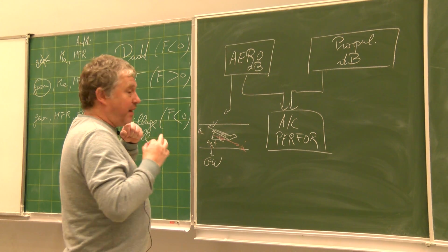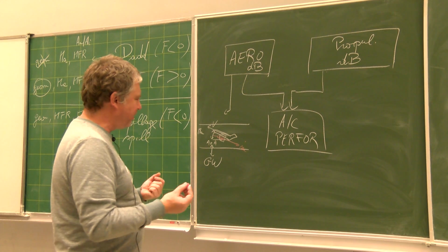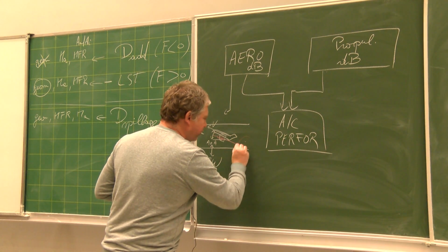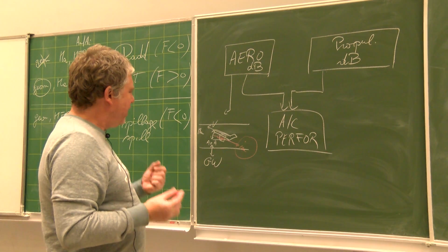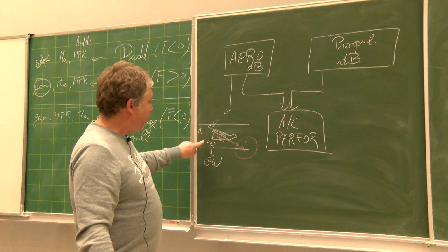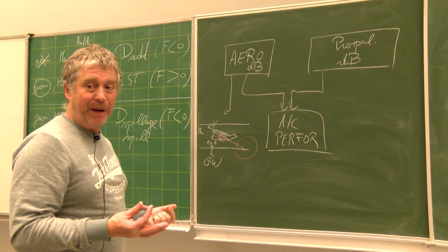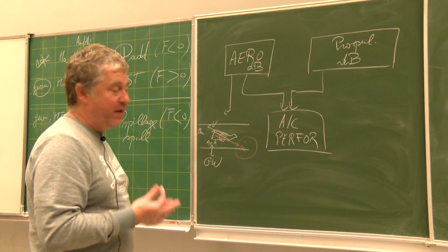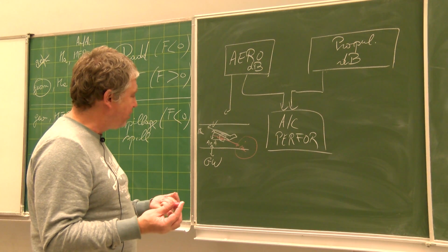And that means that in these very expensive aerodynamic wind tunnels, you are introducing a new parameter, which is the mass flow rate. You would need to make the test for different flight Mach numbers with different angle of attack and with a third parameter, increasing by 50% the number of tests that you need to do.